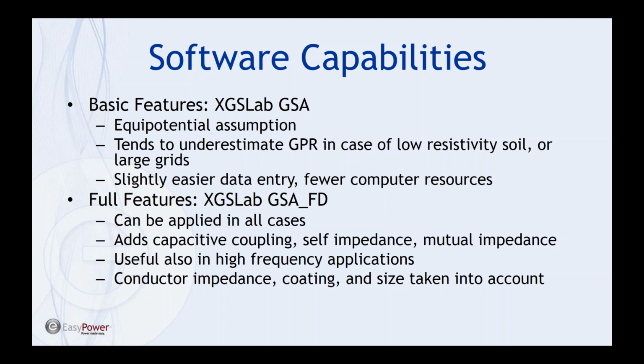Studies have shown generally that the mutual coupling, the mutual impedance, is important, because studies have shown that neglecting it can introduce an error of about 20% into some models. GSA FD does have this, but it's important to note that some of the competitor products don't take mutual coupling into account until stepping up into another level in the software model, module complexity and cost.